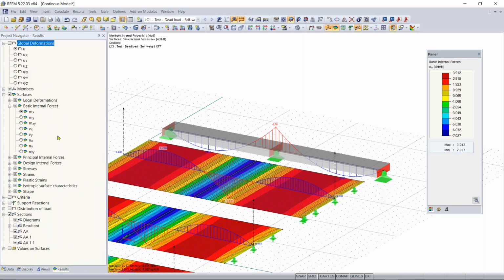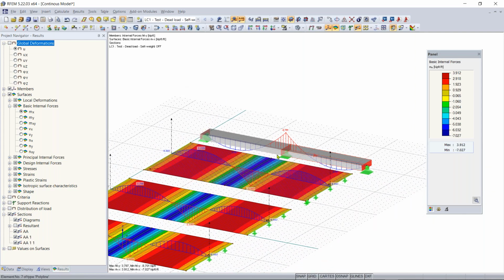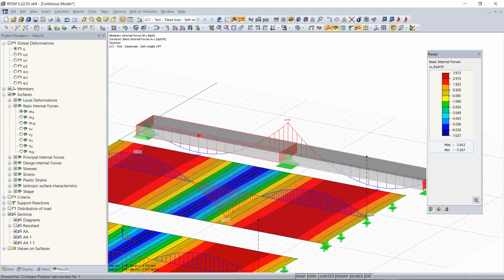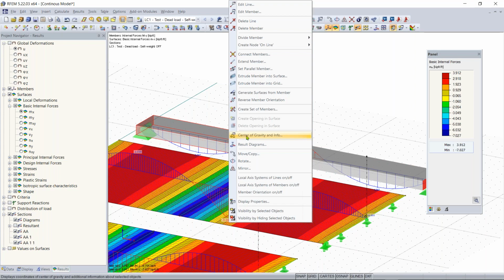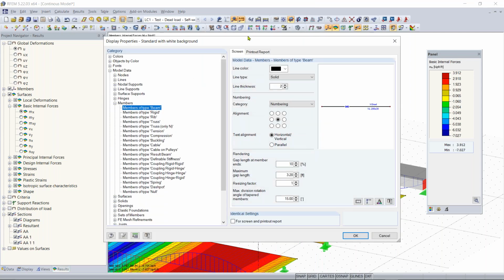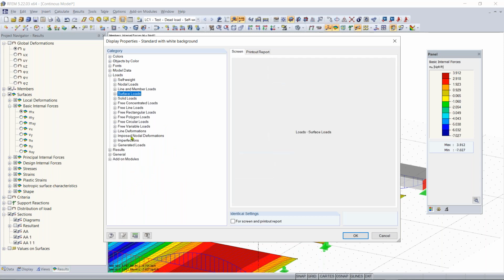And then to get into the second question, can you change the size of the display result numbers? Yeah, so if you're talking about these individual values here, you can change the size of any of these fonts. The easiest way is to click on the member and right click on it. Then you can go down here to display properties. Within this display properties window, you can customize a lot of different things. Right now we'll just customize the fonts.